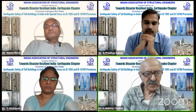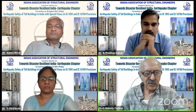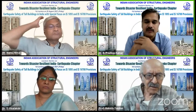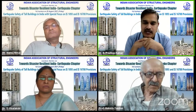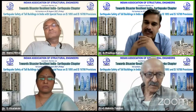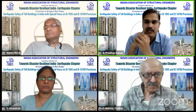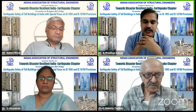Another question is, how do we determine the performance objective of a structure for a specific earthquake intensity? It is the designer's decision, sir. As a designer, we have to design for what purpose our building is intended. Suppose I am designing a hospital building, I decide my performance accordingly, and if it is an ordinary residential building, I decide differently. The structural engineer will decide that. If it is a secretariat building, a government office, or maybe a nuclear power plant, all these are decided by the designer for the intended purpose.